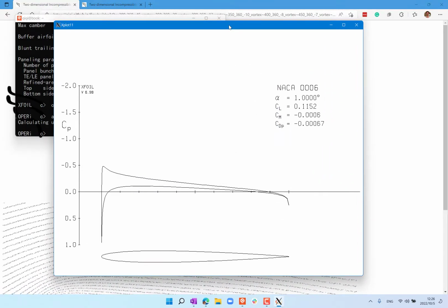You get the pressure distribution, and the difference between the upper and lower surfaces is really the vorticity strength. And this function is that distribution of vorticity you get. It's very high near the leading edge, and it shrinks and becomes 0 at the trailing edge. So that is the function you guys can reconstruct by placing these vortices.